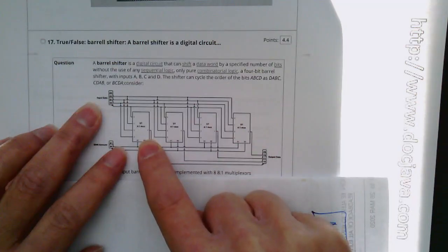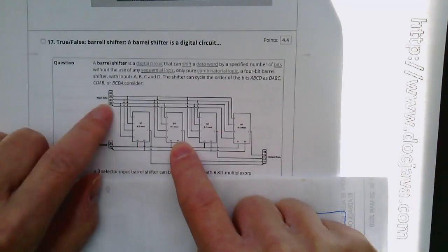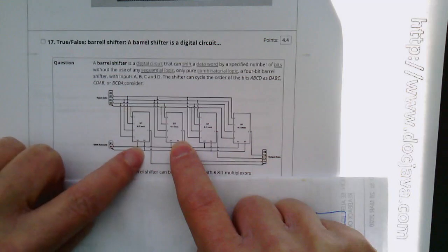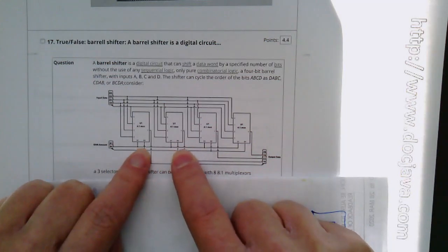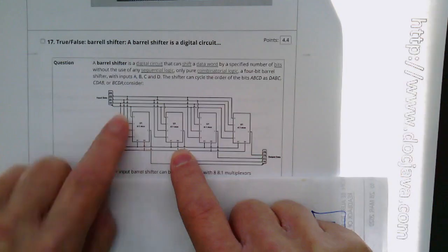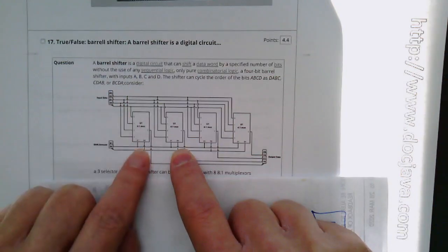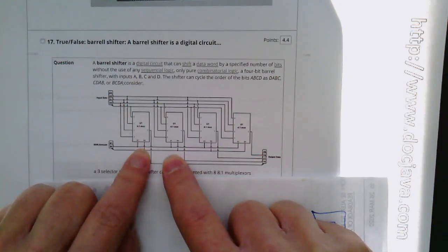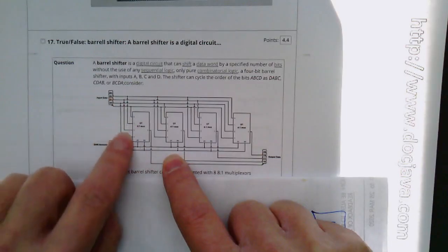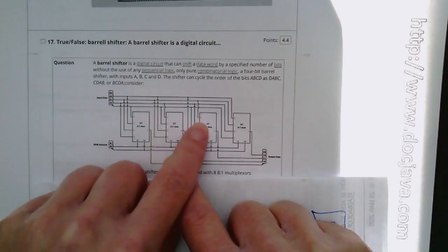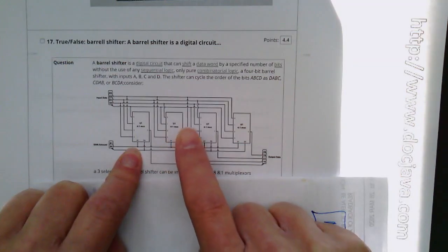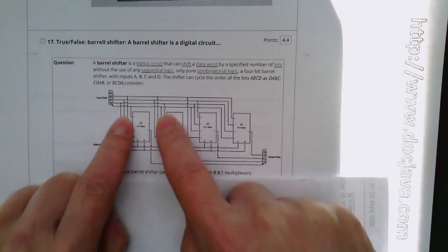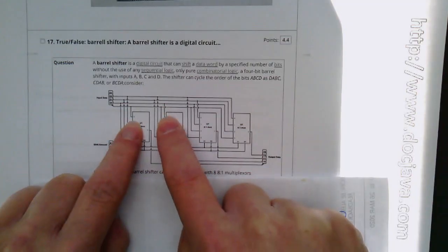multiplexers. And so the multiplexers essentially can choose which input goes to where. And you can do that with this little address thing. So this little addressing thing says which bit will come out of here, and you can choose one of the 4 bits. And so by using this technique, and because the bits are rearranged depending upon which multiplexer you're on, you can choose to pick any one of the inputs, and they're all wired to different places.